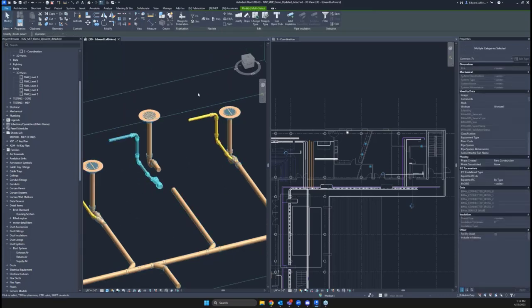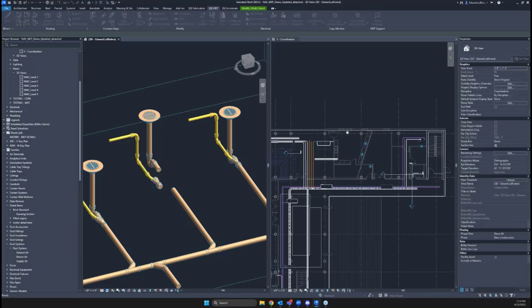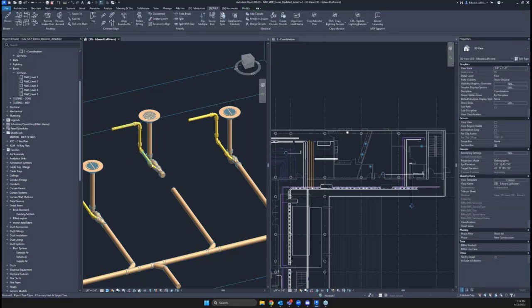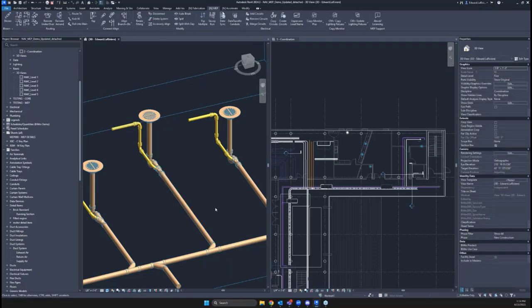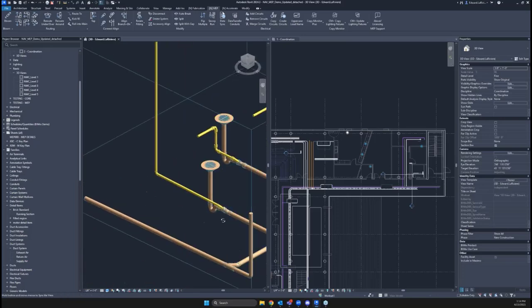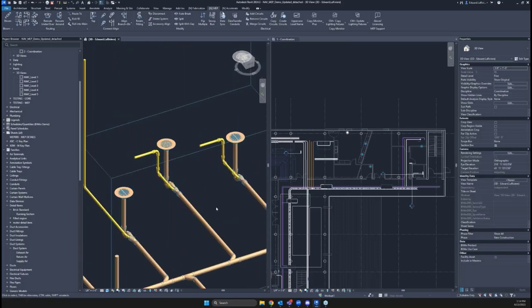If I leave the whole thing selected, then use Move Connect, we'll find it treats it as a group while it moves it into place. If we use Move Connect on a straight element, we'll find it extends it into place. So we'll actually learn that several of our commands have multiple functionalities.